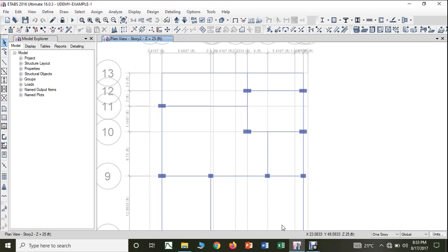Now let us take this plan. We have oriented all the columns from left to right, that is, along the x-axis. Let us check whether those orientations are suitable for each column position or whether we have to change.